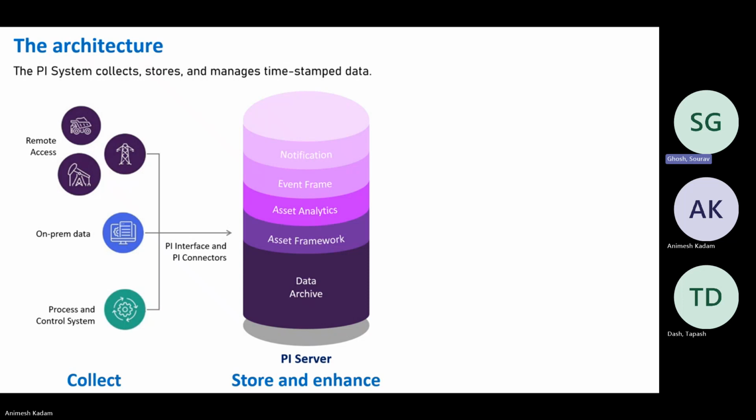So you're saying there is no SQL involved in this Pi system for storing the process data? The SQL is not involved in storing the process data. The major chunk of your data will be your process data, at 1 minute, 5 seconds, 10 seconds, whatever frequency you choose. Whatever data is coming from your equipment is called process data, the real-time or time series data. That data is not sent inside the MS SQL. That data is sent to the Pi data archive files.